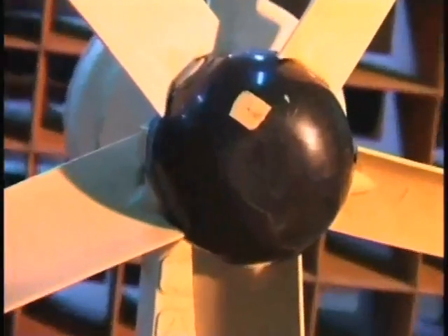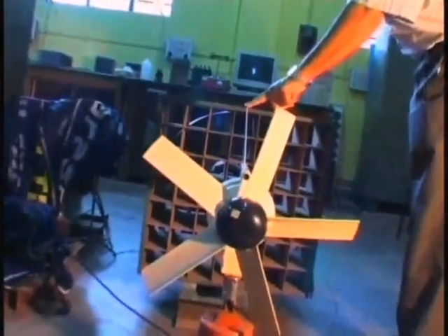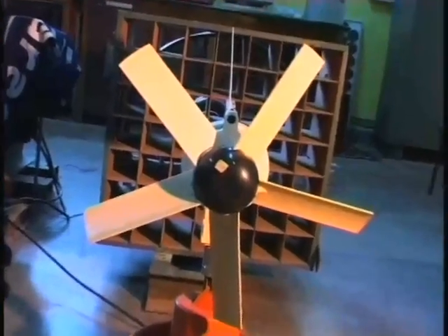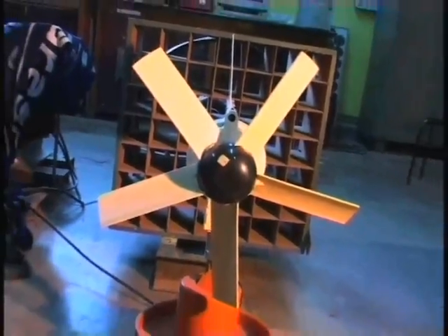So this is the front view of the model wind turbine, and normally this is not rotating now because wind is not blowing. Normally it will rotate in that direction. And here you can see the tail vane which is used to orient the turbine in the direction of the wind. So as the wind blows, this will feel a force and that will automatically orient it to the direction of the wind. Since it is a very small wind turbine, one can use the tail vane for this purpose. For larger wind turbines, you need an automatic motor control mechanism for this orientation.